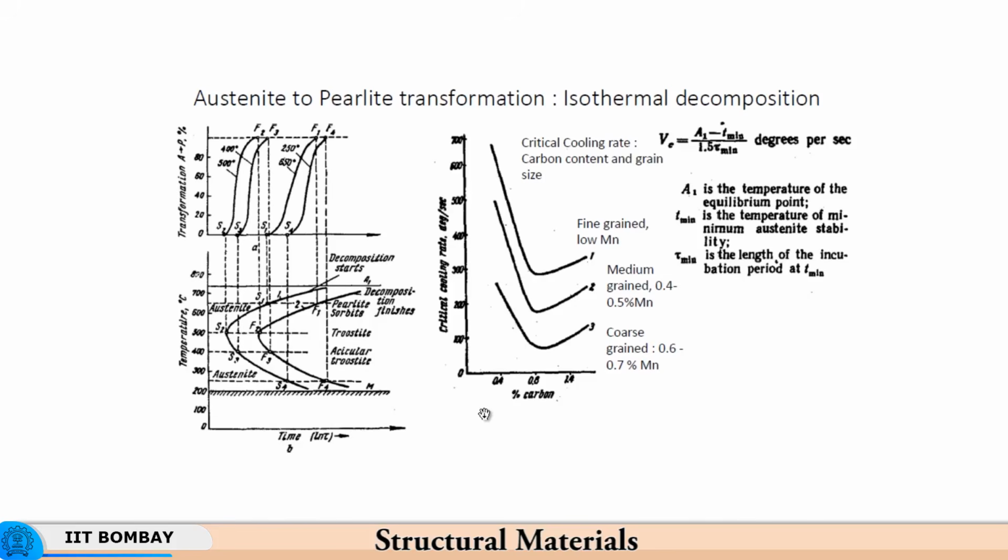Now, for example, in the case of tool steel, where the carbon percentages are of the order of 1.5% carbon, you will get martensite even if you leave the material in the air. So you austenitize it, you heat it to austenitizing temperature, and even if you cool it at a relatively slower rate, you will get martensite, even at a slow cooling rate. This means that you can avoid the generation of these stresses and subsequent cracking by cooling at a relatively lower cooling rate, and yet you get martensite. So you get the hardness, but without any cracking.